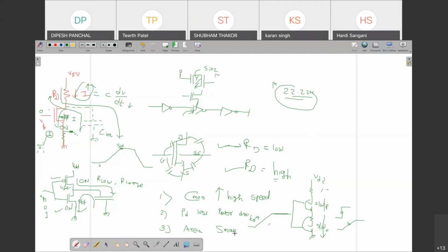Whenever a large interconnection is there, whose critical delay is very large, you have to break that wire into small pieces, and you have to use a buffer in between, that matches the impedance of two lines and your propagation delay is reduced. So in interconnection, definitely we have a use of buffers.